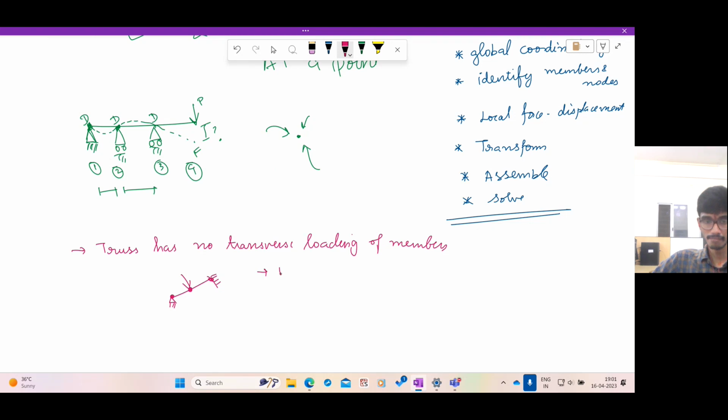So if you have a beam element, you ensure that you choose the beam elements such that there are no span concentrated loadings. So again, that is just a convenience. So it basically means you have something like this. Don't discretize it as one element. So this is wrong, because you will not be able to capture the effect of this.